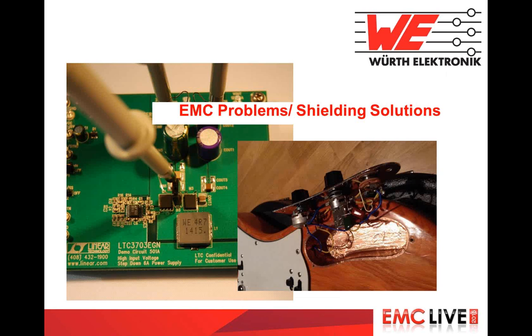So where's the problem then? If we have conductive shielding, we have hundreds of dBs of shielding attenuation thanks to the reflection. Why do we need to make a webinar talking about this? The problem comes when in our device we cannot just wrap it with copper or aluminum, because we need some cable entries, connectors, displays, ventilation, or apertures just for maintenance or in the assembly process.